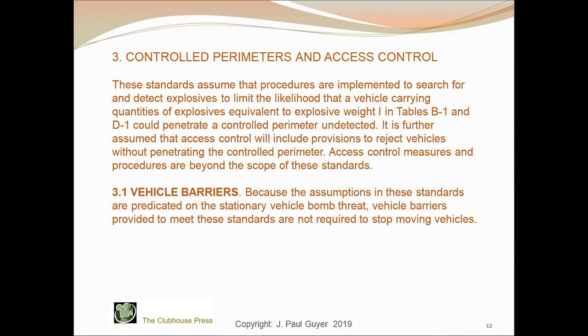Vehicle barriers: the assumptions in these standards, what we're talking about today, are predicated on a stationary vehicle bomb threat. The vehicle barriers described in this discussion are not intended and not required to stop moving vehicles. Again, this is based on unfortunate experience where the vast majority of terrorist acts have involved a stationary vehicle.